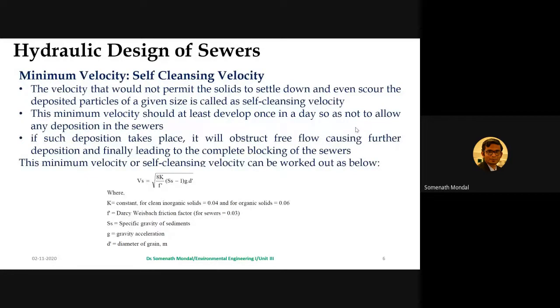So we have K, the constant for clean inorganic solids, it is given, and as well as for organic solids it is given. So you can choose the value depending upon what type of solids that particular liquid or the sewage is containing, and accordingly you can take the value of K. f' is nothing but the Darcy-Weisbach friction factor.